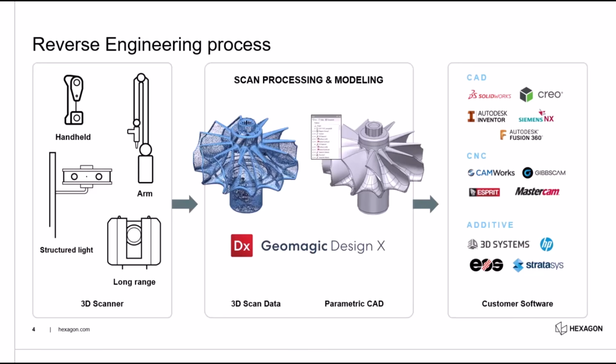So by far the top section there is the number one output, where we have a live transfer tool that will allow you to transfer over the CAD information as native entities over to these different CAD platforms. The second one down is we can then save out models like STEP, IGES, and neutral, all these different native interchange formats to send over straight to CNC packages for cutting stuff directly, or additive. Some additive packages will take CAD models or meshes, and we can save out to those as well.